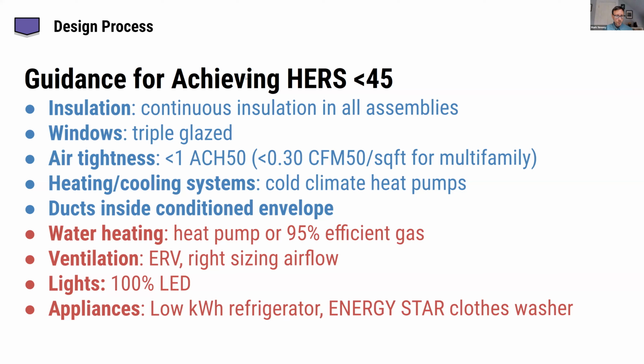And then the last envelope item here I have is getting your ductwork inside the conditioned envelope so that you don't really have much for duct losses. Having your ductwork in the attic is a loss that you may not have room for if you're trying to hit a HERS index of 42 or 45.